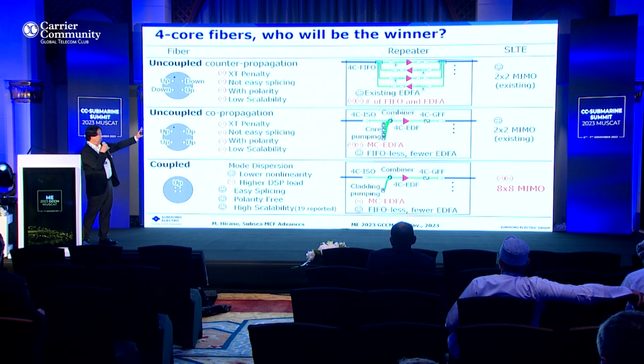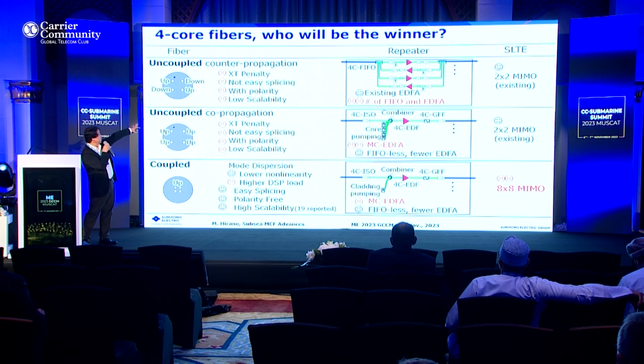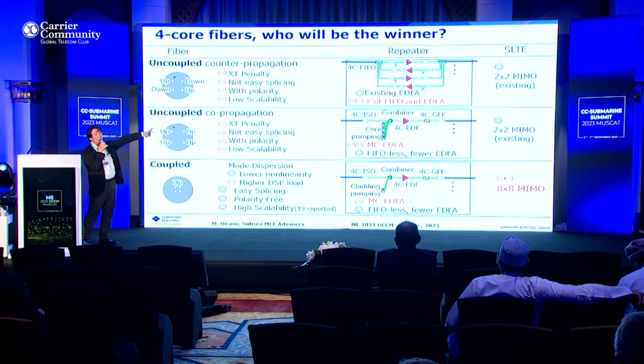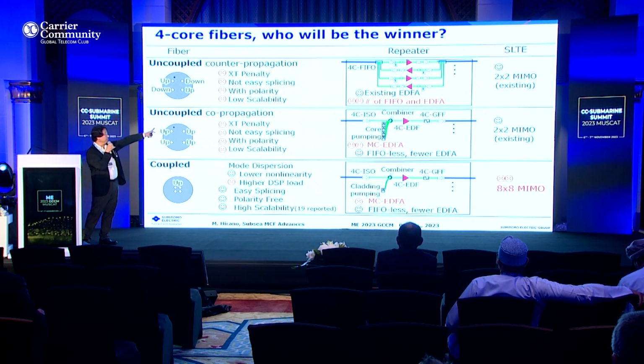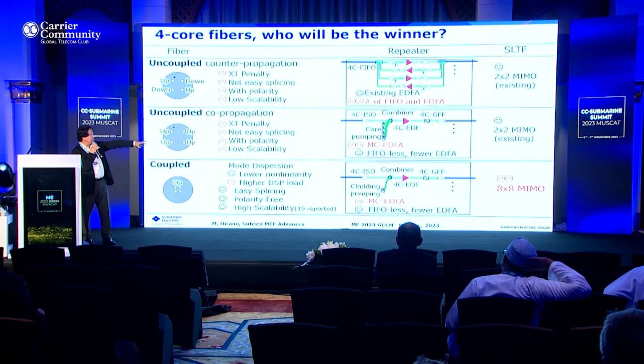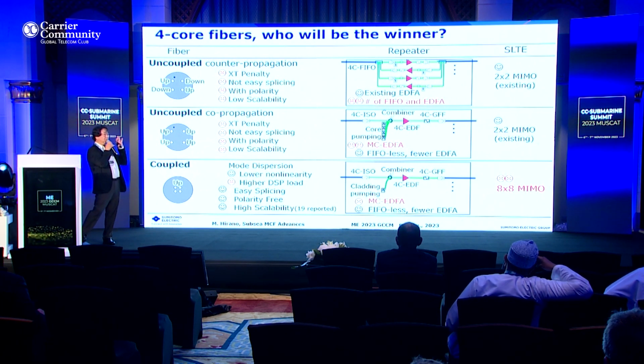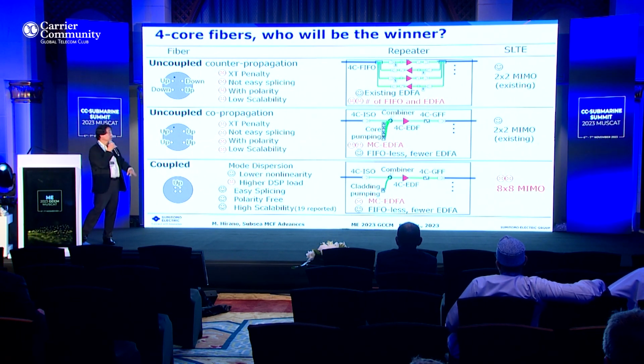Repeater. Okay, for the counter-propagation scheme, you cannot use a multi-core EDFA, and you need many EDFAs. This is not good news. For the co-propagation, you can adopt a multi-core EDFA because the signals move in the same direction.